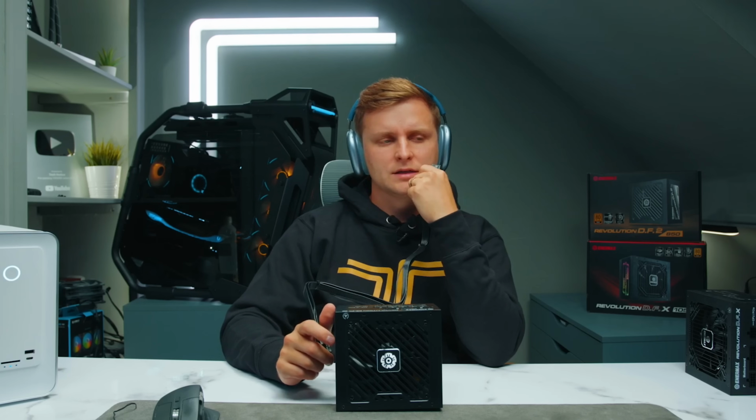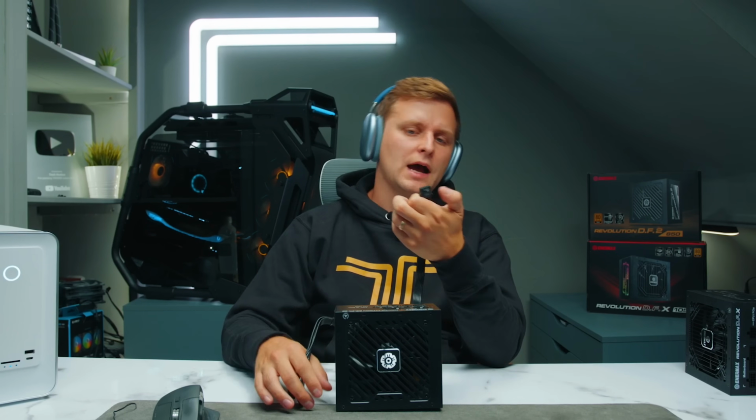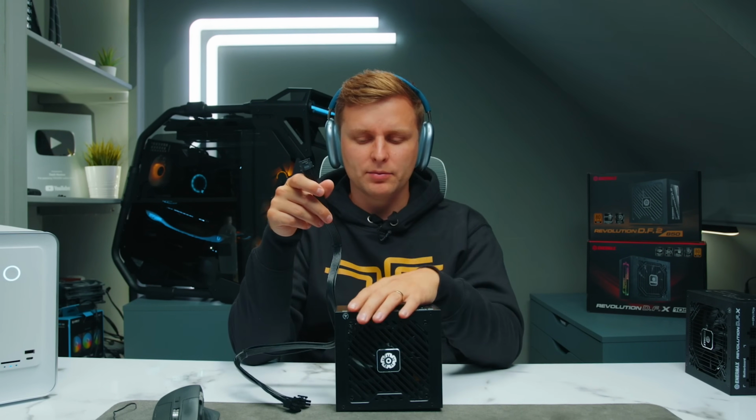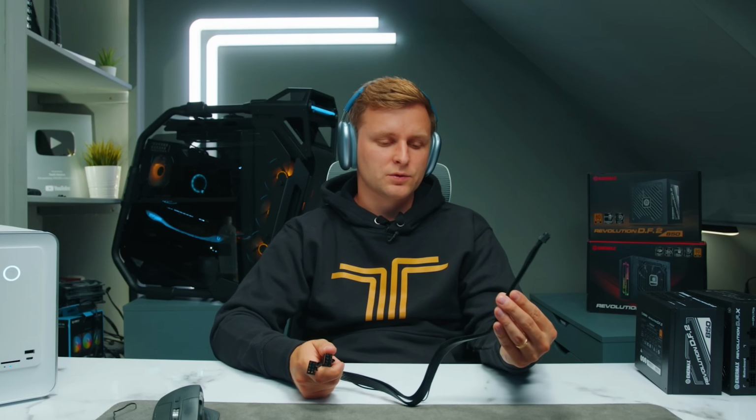Another question I have is, in terms of the 12 volt high power cable, obviously this is a new cable, and one of the benefits is that it delivers more power per cable compared to the PCIe 8-pin cable, which I believe is 150 watts. This 600 watt power cable gives you more power per single cable compared to the previous generation. NVIDIA gives you an adapter where you have to plug in 4 PCIe 8-pin cables to get one of these. So, fewer cables, more power.